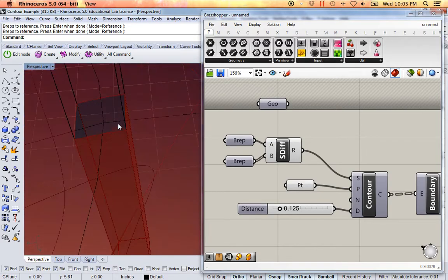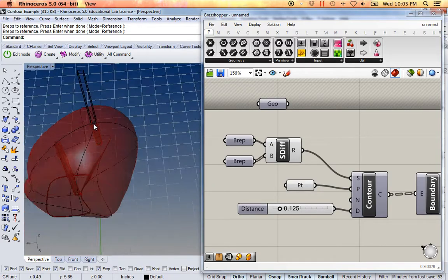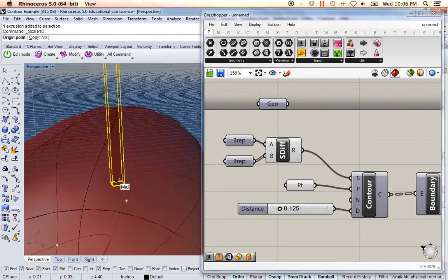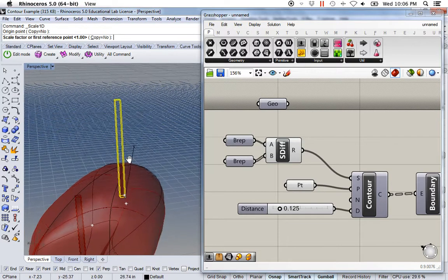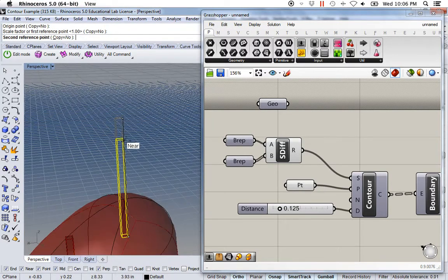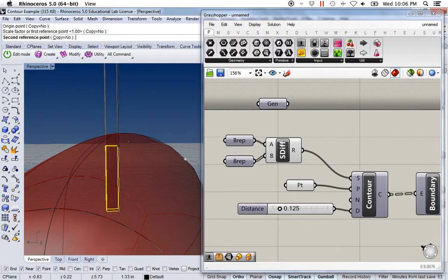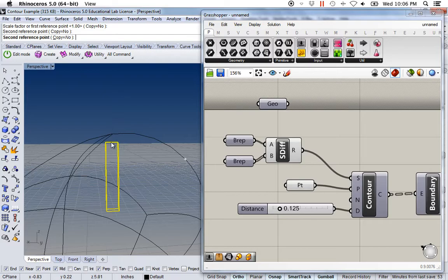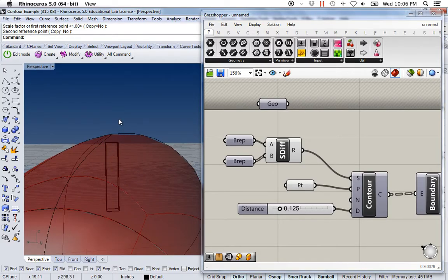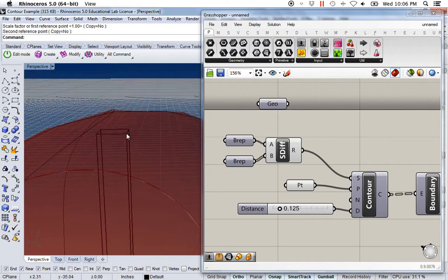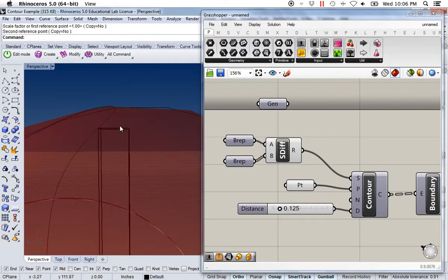The only trick is now this one is cutting through on the top. So if I try to make this one smaller, scale 1D, I'm gonna run into an issue, and that issue is I'm gonna want this to be just slightly below the top surface. The only problem is once it goes inside the surface, the Boolean command doesn't work.